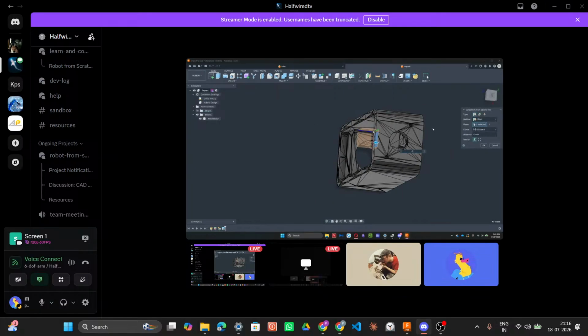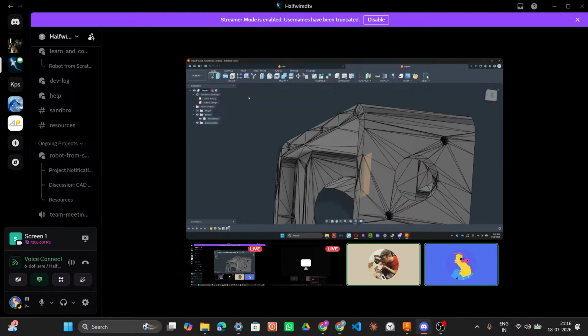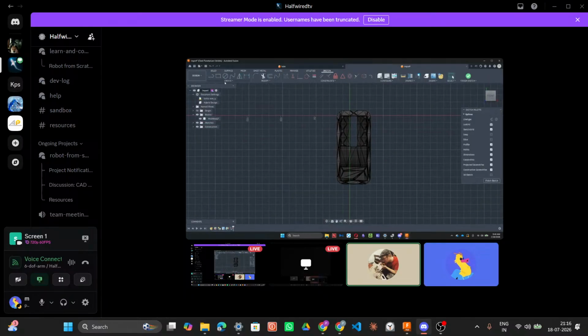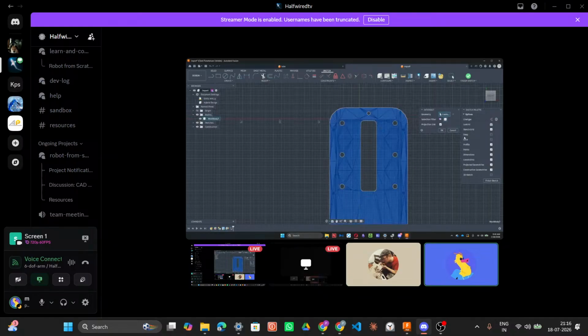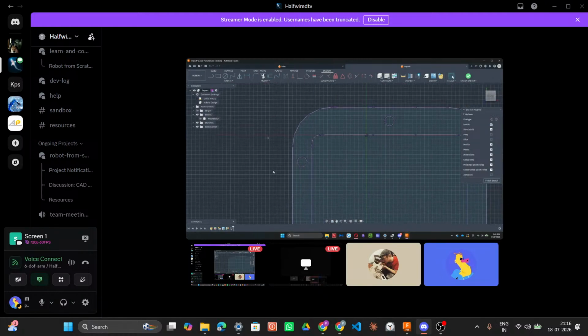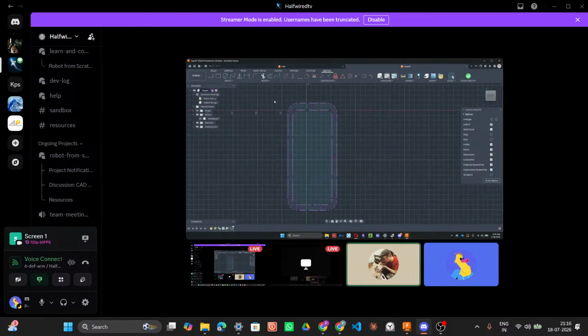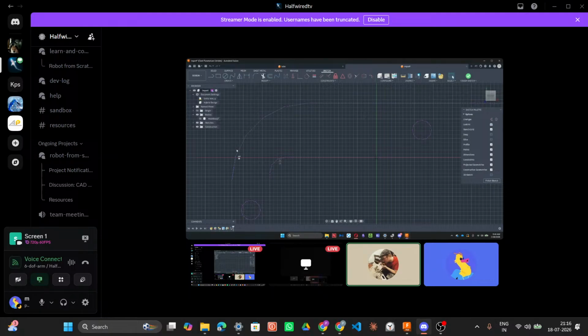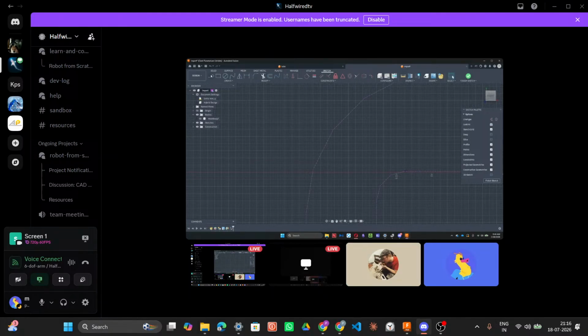So if I did a plane 1 millimeter down and create a sketch on there. Now, if I do a project and then an intersect on that body and then hide it, it creates points. Then I get all of those. What I'd still usually do is highlight everything, hit X to make them all construction lines so that I'm not dealing with these weird facets.